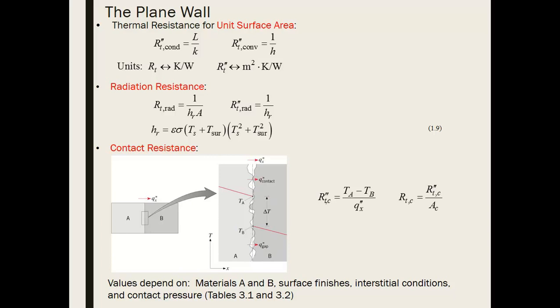So that's when there's not perfect contact between two different media, so there's not going to be really great heat transfer, and one way to characterize that is to just say, well, these two surfaces have a contact resistance, and you'd basically just get that number as a constant from somewhere. You don't need a thermal conductivity, you don't need a convection coefficient. You just either experimentally determine that number or find it in a table somewhere.